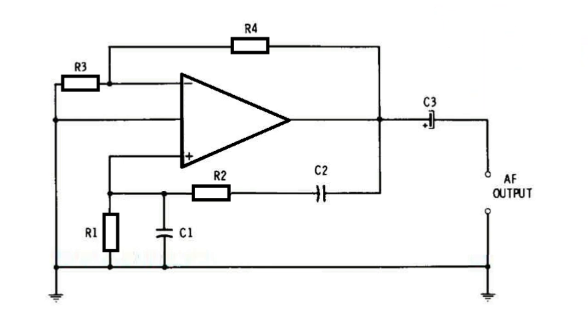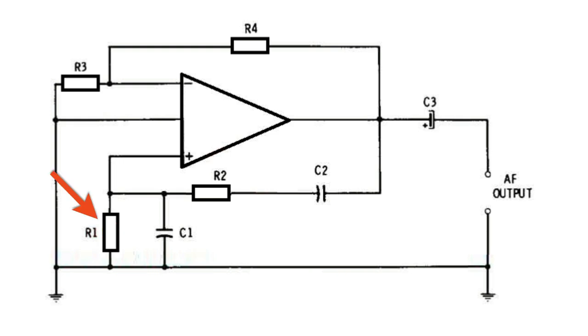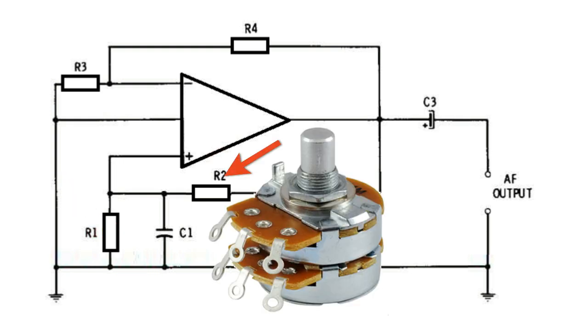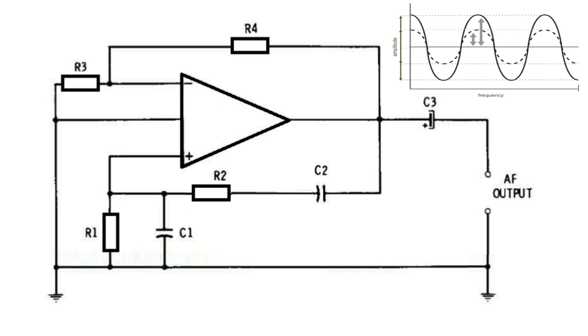This form of Opamp oscillator circuit can be easily turned into a continuously tunable oscillator in the range of 20 Hz to 1 MHz, simply by replacing the resistors R1 and R2 with a dual-gang potentiometer, and by ensuring that the capacitors C1 and C2 are switched in pairs in order to adjust frequency bands. The tuning of the oscillator circuit can be implemented over a large frequency range, but its output signal amplitude might show a varying tendency with respect to the frequency.